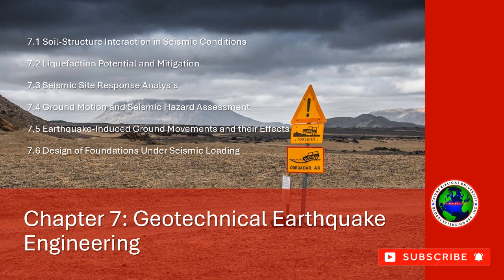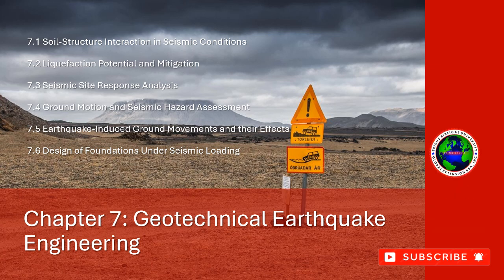3. Ground improvement techniques. Vibro replacement. Vibro replacement techniques, such as stone columns or gravel piles, can be used to improve the strength of liquefiable soils. These methods increase the soil's shear strength by introducing dense materials into the soil profile.